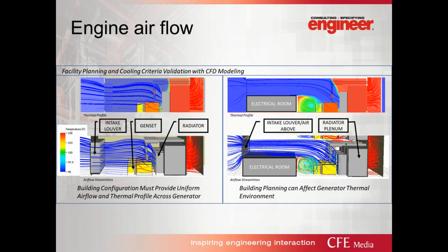Airflow. When you have a packaged outdoor unit by one of the vendors, oftentimes they go through that engineering task to make sure that you have proper airflow across your engine. If you want to have a more hardened facility and have your generators protected indoors, that's the job of the engineer to worry about that. If you have a large generator system and you have 4, 5, 6 or more 3 megawatt engines in the same room, that's a tremendous amount of CFM that you have to deal with. The louver size gets very big, and if that's not understood on the front end of the project, the form factor of the building and the aesthetic are greatly impacted.